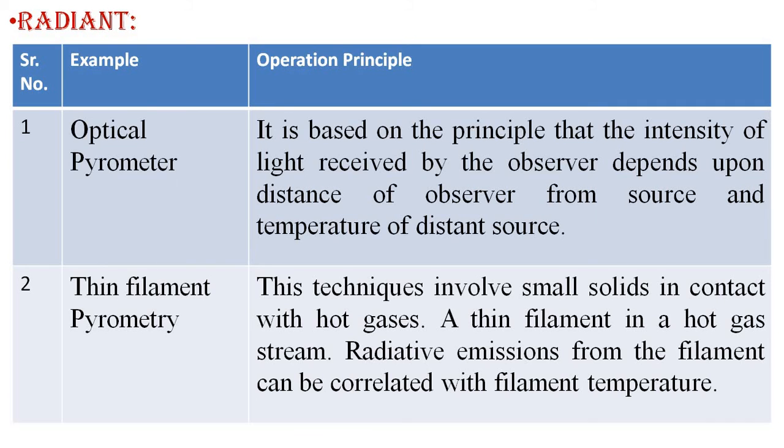Second, thin filament pyrometry. This technique involves small solids in contact with hot gases. With a thin filament in a hot gas stream, the radiative emission from the filament can be correlated with the gas temperature.